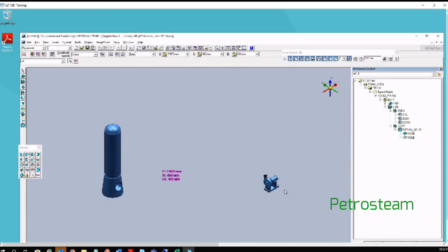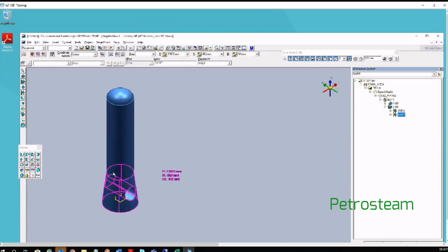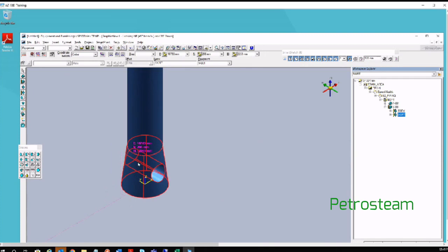There is a pump placed using this catalog equipment placement, and we have built this designed equipment, vessel V001, whose body we built using one cylinder and two dish ends, and the skirt we built using a positive cone and negative cylinder. If you wish, you can suppress this negative cylinder shape so that there is no impact for the time being.